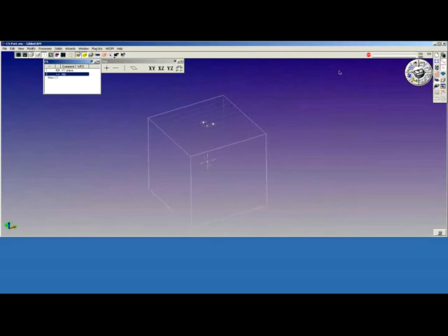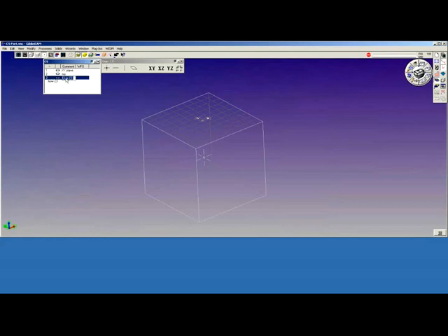And we're going to create another coordinate system, but this next coordinate system we're going to place on the front of the cuboid. This CS is going to require different planar orientation, so we'll generate a CS, change the origin and the planar orientation to place it on the front of the cube. So the new CS is generated by clicking on New CS. I change the name of it, call it the front.